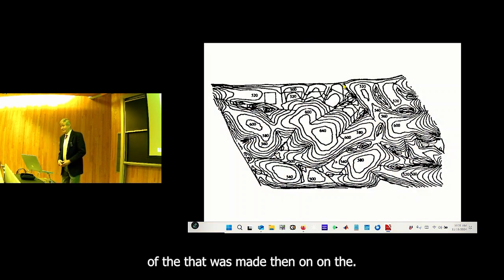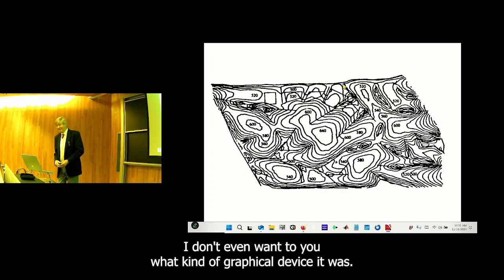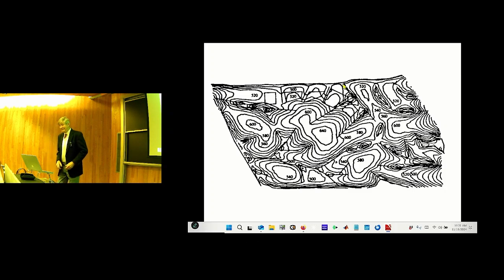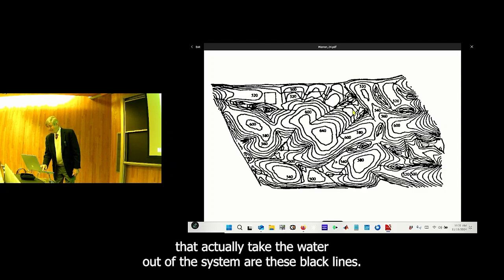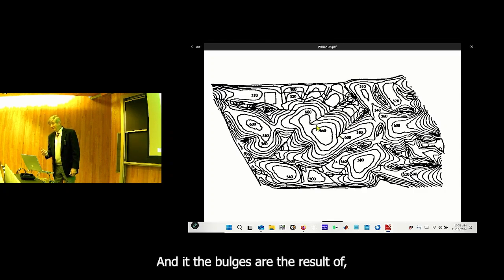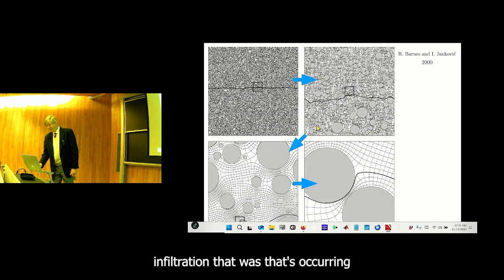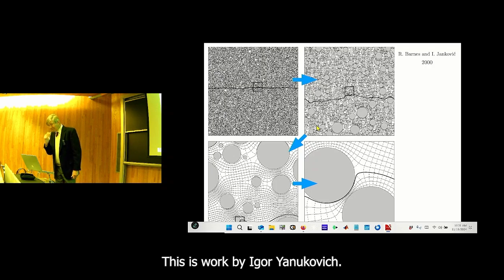This is a picture that was made then on a, I don't even want to tell you what kind of graphical device it was. It was huge. And so the contour lines are energy lines, if you like. And of course the flow is again down those lines. And the line sinks that actually take the water out of the system are these black lines. And the bulges are the result of infiltration that's occurring.